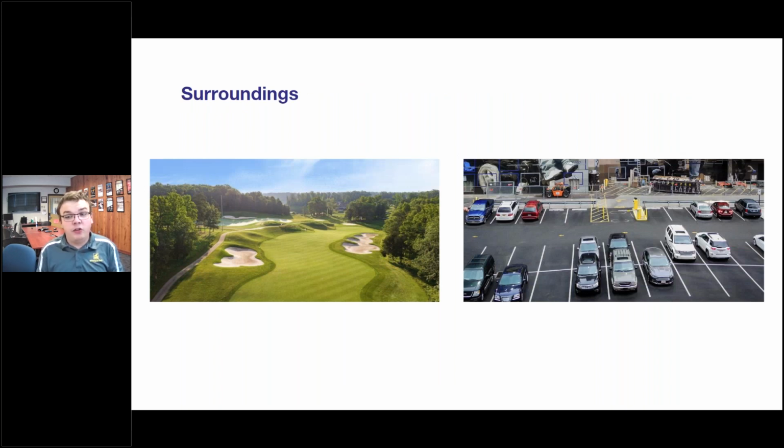This is especially true for combined sewers, but the surroundings around a lagoon can play a big part in what you are going to be dealing with on a daily basis. If you have green spaces, a lot of agriculture, golf courses, nice green manicured spaces that get a lot of fertilizer on them, or kept very short grassed areas, then if it rains and you're on a combined sewer system, all of the nutrients that were placed on the golf course are going to wash off. Some of it's going to get absorbed into the soil, and that doesn't reach you.